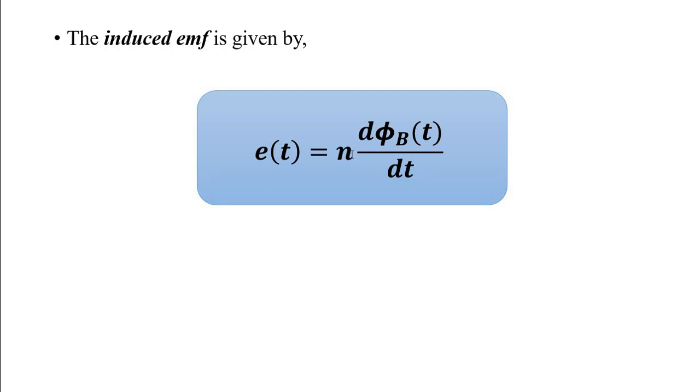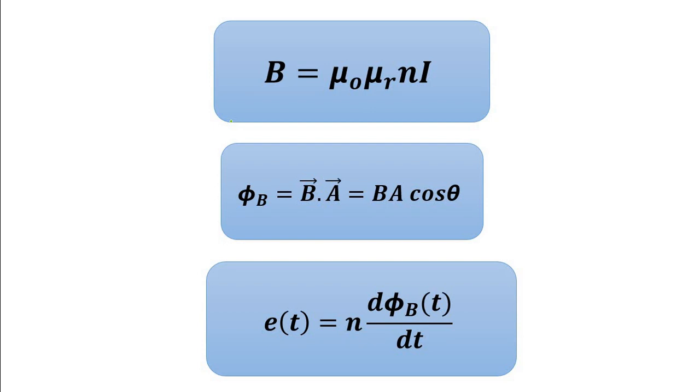Well, in some cases the direction of the EMF induced is also important, but for now just focus on this. Okay, so here this is the sequence of events. Relative permeability causes a change in magnetic flux density. Magnetic flux density causes a change in magnetic flux. Change in magnetic flux produces an EMF, and all these things are constant here. Okay, so how can we use it for measurement of displacement?